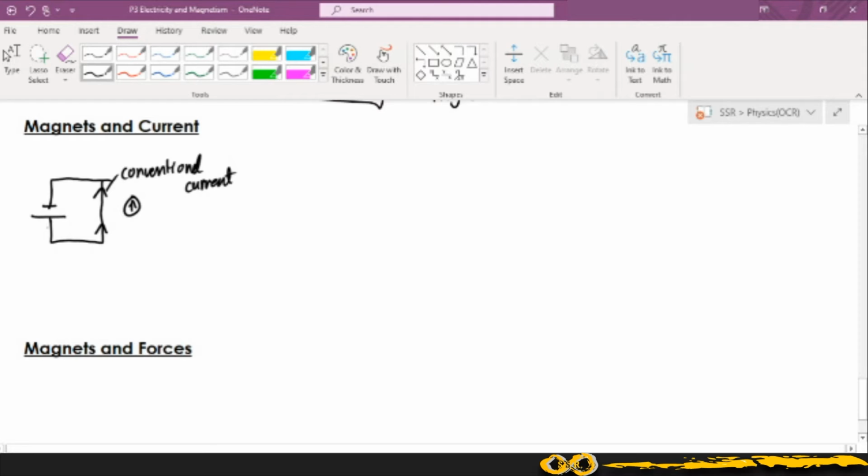And he came up with what is known as the right-hand rule in order to determine the direction of the magnetic field. So if you picture your right hand with your thumb extended in the direction of the current, and then the fingers of your hand are curling around, and you'll have to excuse my hand drawing here. The fingers of your hand are curling around in order to grab the wire with the current flowing in that direction. The way that your fingers are curling around the wire is the direction of the magnetic field. The closer it is to the wire, the stronger it is, and the further apart you get, the further apart your magnetic fields are. And then you draw in your arrows to indicate the direction of the magnetic field curling around the wire.